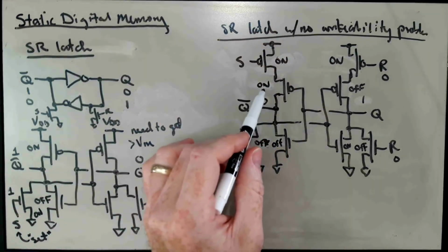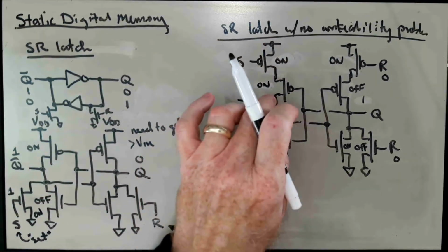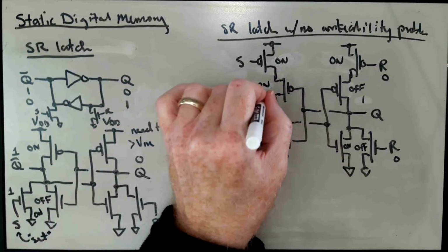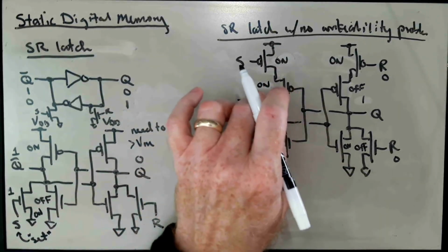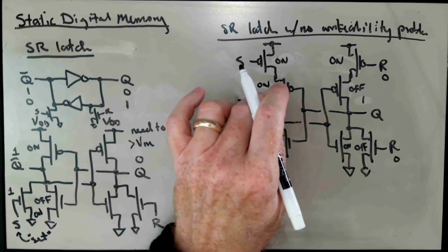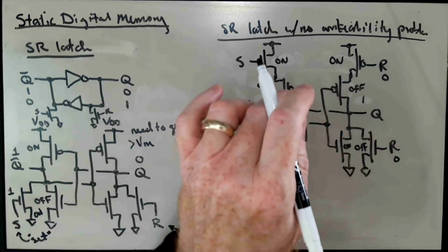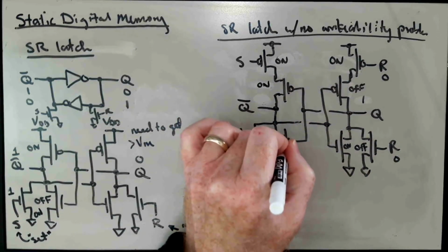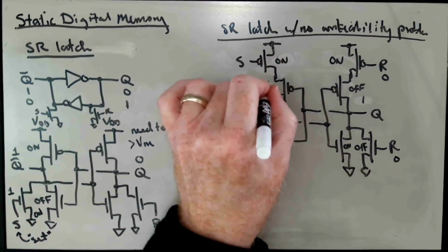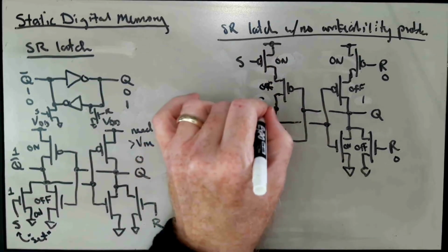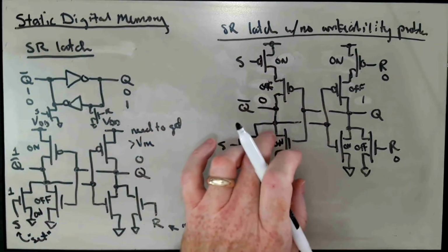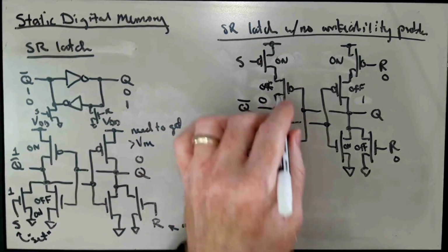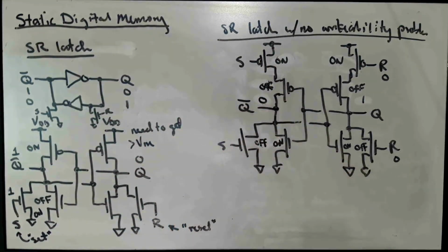We basically have successfully flipped the state so that, I'm sorry, this is on and this is off, and so this would be set to 0 or maintained at 0 by the state of the two transistors in the feedback here.